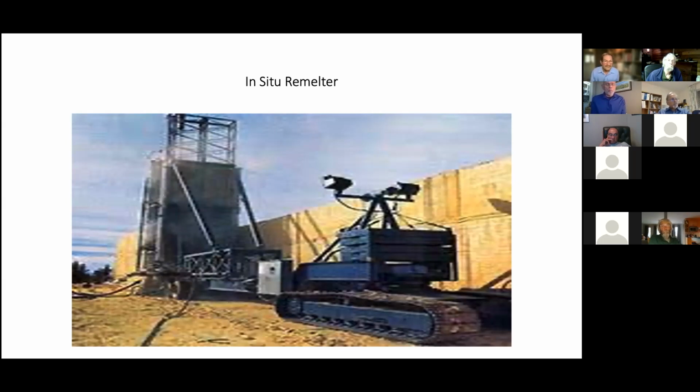The problem with this is you can see it's very fumy around the melting area. It has lots of emissions, and the steam coils corrode. Because they're typically carbon steel, you have to use very thick ones. You can go schedule 80, but anything more and you don't have the heating efficiency. It has worked, but nowadays, because of the environmental emissions and all that, it's fallen out of favor for quite some time now.